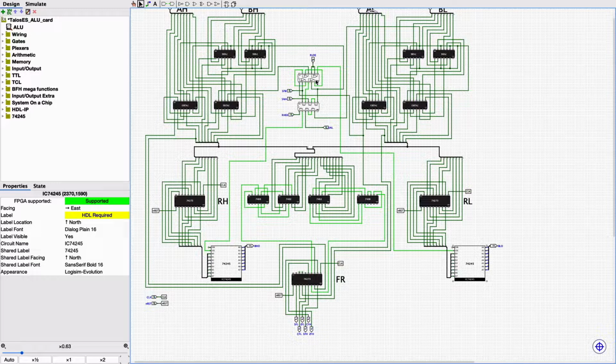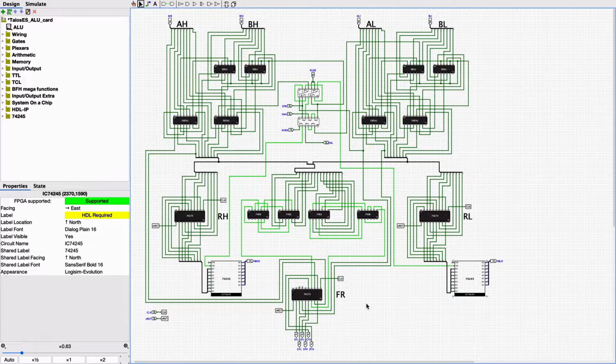So these are some of the reasons why all the control signals that get into a card always pass through some kind of gate, usually an inverter gate or a pseudo-inverter gate like this NAND gate, to have their levels boosted and to correct some of the EMI, the electromagnetic interference, before they actually play their logic role in the circuit. So that's pretty much it.